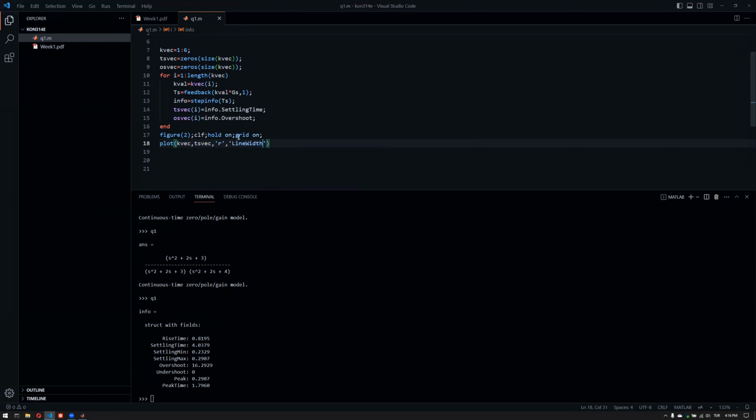Let's give it a line width. Let's also give it a display name. I like to use this display name because now this is called TS, for example, and when I open a legend here and tell it to just show, I don't really care about the order of the legend, because every name is attached to the plot itself, so it will show automatically the correct name for the correct plot. If you don't use this display name, you can also provide the names like this, but if you change the order, you have to update the legend, and I don't really like to do that.